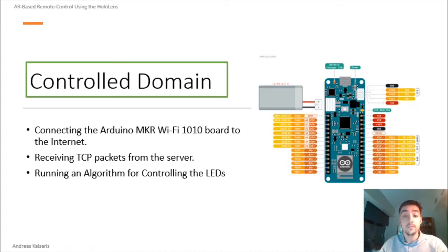The development of this domain started with the connection of the Arduino board to the internet using the Wi-Fi shield to connect to a 4G mobile network. Then a script was written in the Arduino IDE that opens up a port and waits for TCP packets to arrive from the project's Python server.